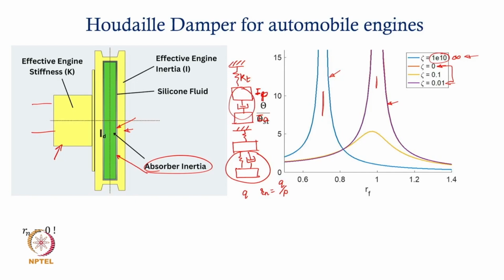The two masses will club together, and then you will have a single degree of freedom system, and the mass being heavier or larger, your frequency will drop, it will be lower. With zero damping, the absorber is sort of not there at all, and then you have a higher frequency. Okay, what is the response for an intermediate damping case?